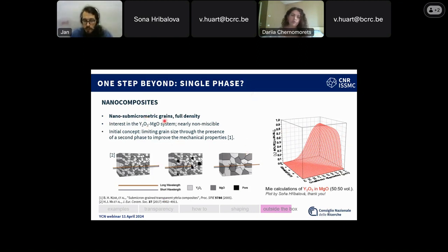The first powder is characterized by soft agglomerates, and it can be easily broken as a result of planetary ball milling. After milling, the primary particle size is on the nanometric scale, so probably we can expect uniform microstructure and high density of the green body with this powder.